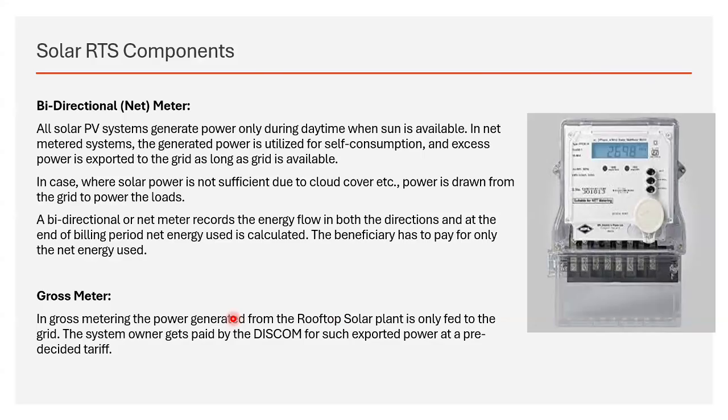So if we wish to generate energy and push it to the grid, and the purpose is sale of power to the utility, then we don't need to invest much in a bidirectional meter. We can have a gross meter.